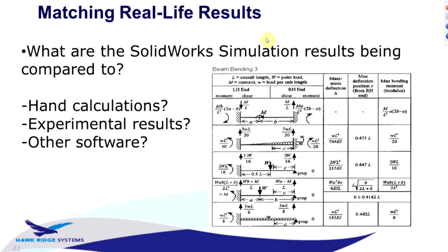But most likely the geometry of whatever you're trying to run your analysis on in the software is not exactly the same as whatever that equation was derived for. It's probably not a simple cantilevered beam, fixed at one end with exactly the same length and section properties and all those assumptions. Remember, that's really the reason that FEA was invented in the first place, so that we had another method to evaluate the real geometry of products rather than trying to assume that they're just an idealized shape.